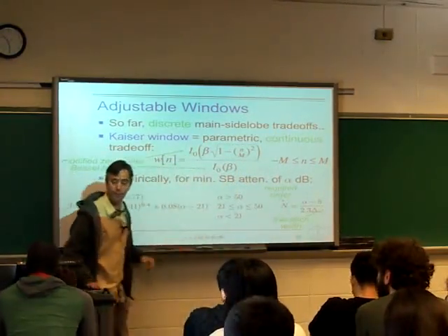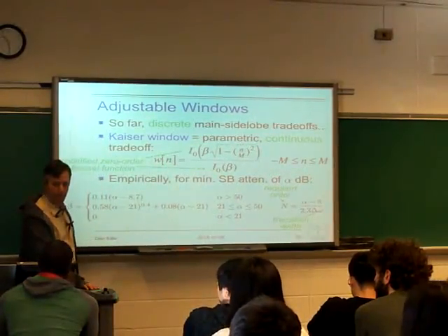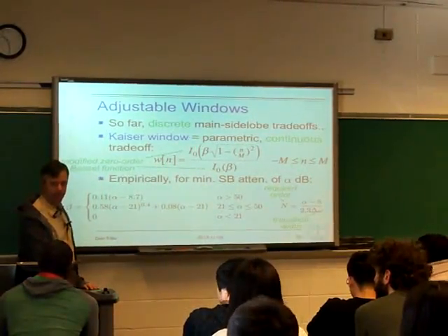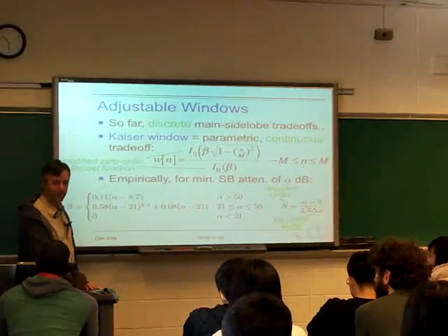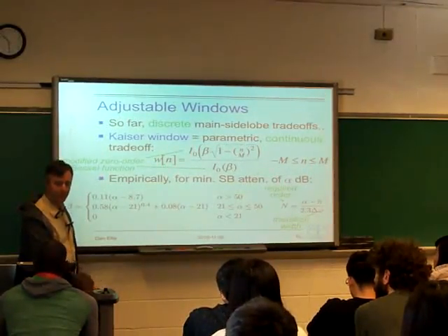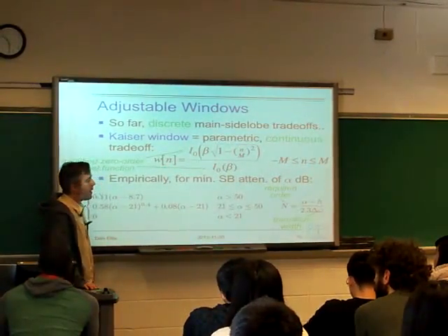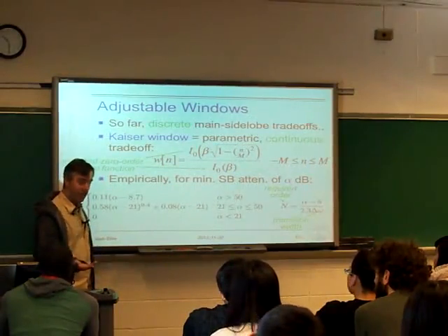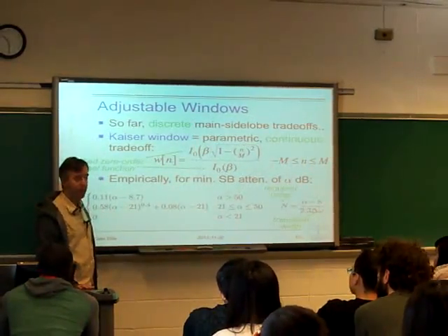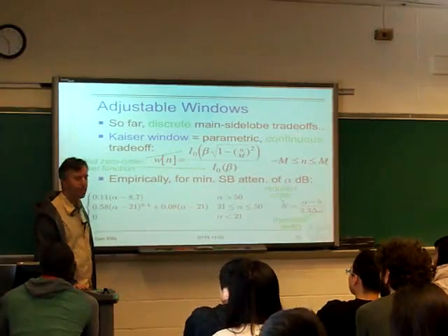Yeah. So is it a good idea to maybe use one of the, say, the Hanning, and to get rid of the other high frequency stuff, add a low pass filter to better attenuate the high? Right. So if we've got these side lobes showing up in the high frequency, well, we can just put a low-pass filter on them to get rid of them.